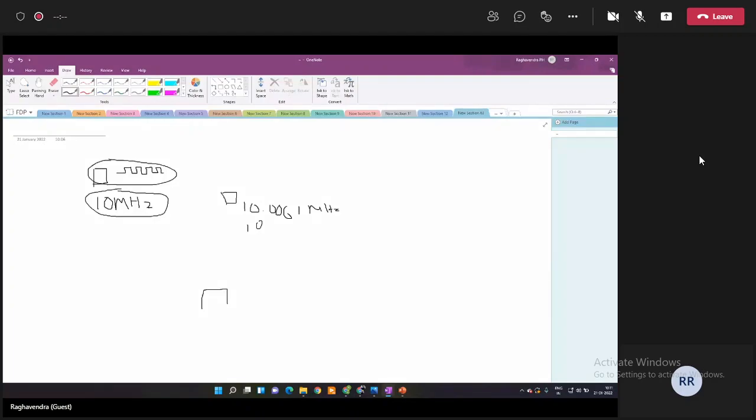Now, let's take an ADC for an example. Let's say my sample period is like this. This may be for USRP1. But the problem is in USRP2, the sampling might start like this. You can see that there is very clearly a phase mismatch between the samples that I take. And this doesn't do us any good because your signal processing just goes all over the place when you try to do this.